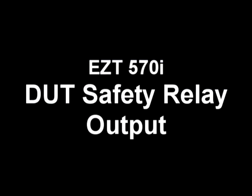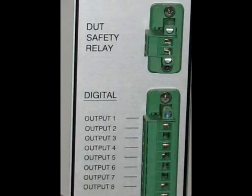The environmental chamber is equipped with high heat limits and other safety devices. These devices remove power from the chamber's heaters only, but do not remove the power from the device under test. To turn off the tested device when the chamber is off, a device under test, or DUT, safety relay is included with the chamber. This relay will open and turn off the device under test to prevent a runaway thermal condition whenever the chamber is not operating.